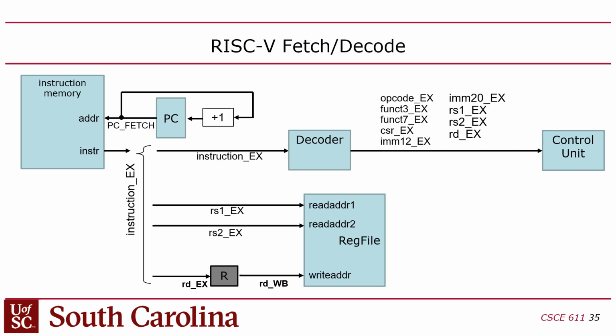So how does that bypass play into this? What that means is if you have an instruction that reads a register that appears after an instruction that writes a register, then you'll be reading and writing that same register in the same cycle. Not from the same instruction, but from two different instructions at different stages of the pipeline. So whatever instruction came second will be reading, and the instruction that came first will be writing, but they'll be doing it at the same time because of the pipeline. And that's when that bypass will activate inside the register file.